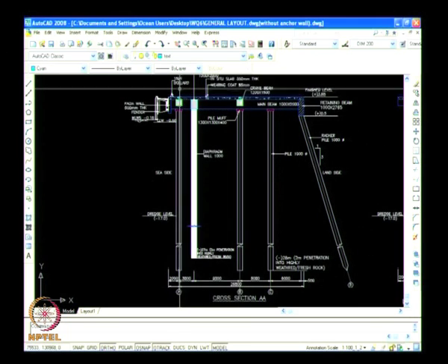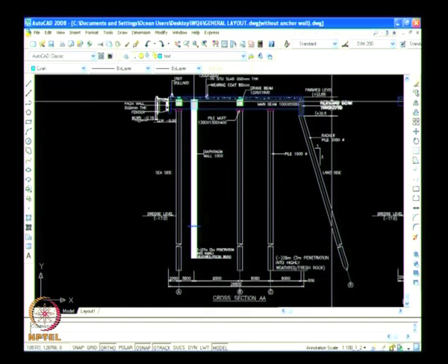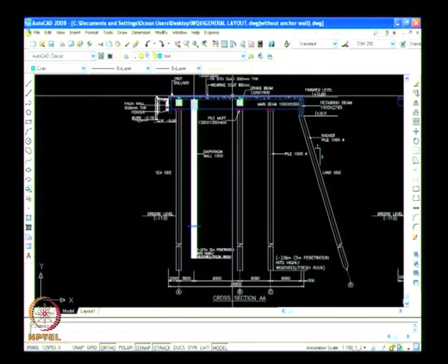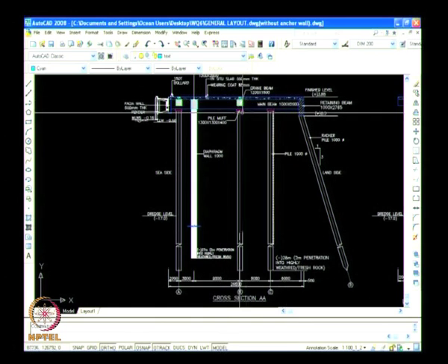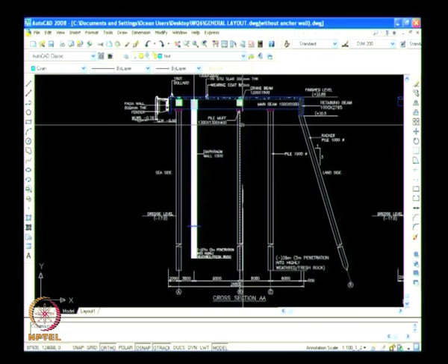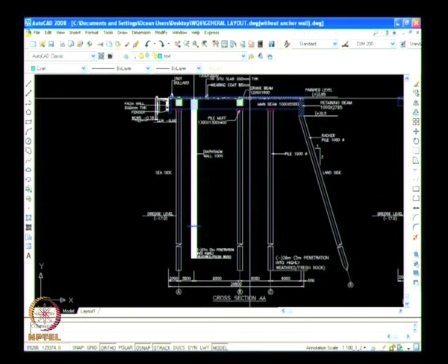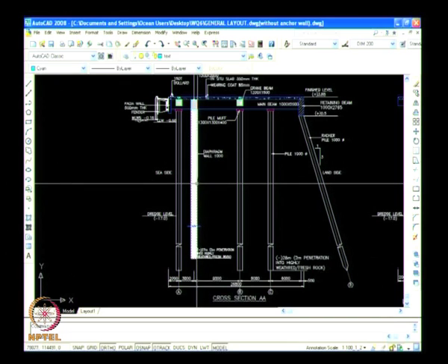there is a load on top of the deck, that is 50 kilonewton per meter square, on the backfill also 50 kilonewton per meter square. There is a rail, another rail over which the crane will move. All the loads on the deck will go to the diaphragm wall and piles, it will not go to the soil below. So if the deck is too close, the surcharge load will transmit some force on the main diaphragm wall, that is why we want to keep it here.